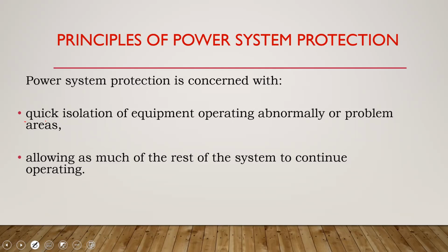So protection, as I said, is quick isolation. So you have to make millisecond decisions. And you have to be able to separate the faulted system from the rest of the system as quickly as possible. And I say from the rest of the system because you want to be able to cause the rest of the system to continue operating.